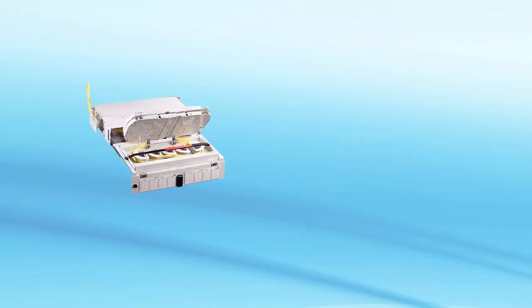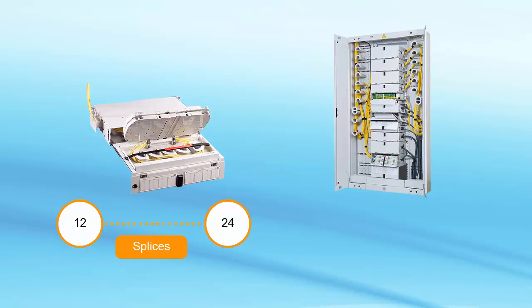The individual splices are housed within a splice tray, generally holding between 12 and 24 splices. The splice trays, in turn, are housed within a shelf or enclosure that can hold anything from 96 up to 864 splices in a single unit. For these enclosures, the most critical fiber cable management features are the bend radius and physical protection. The fiber cable management determines the ability to reconfigure or rework any splices.